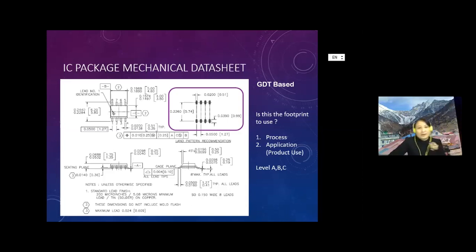I'm just showing you an example of a very typical mechanical data sheet with a land pattern. And is this a footprint that you're going to use? Some of the customers, well, half of them said that, yeah, they normally use this. However, if you're just doing a regular consumer-based, not so critical kind of design, it is okay. But however, if you're doing a class 3 design or even class 2, you have to be careful in terms of this particular land pattern that you create.